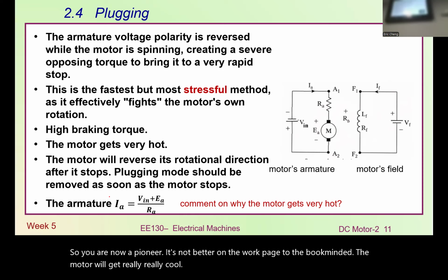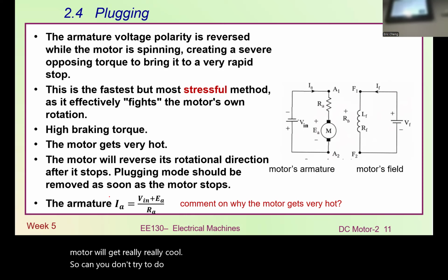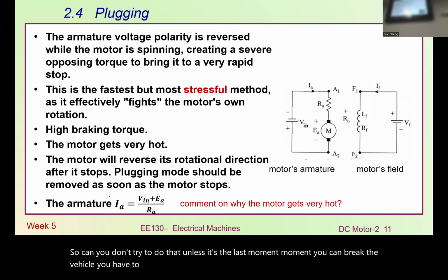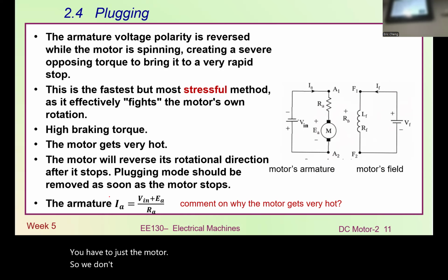So you don't try to do that unless, at the last moment, you cannot brake the vehicle and you have to use plugging mode for instant, sudden braking of the vehicle or the motion. So we don't use that until the last millisecond, when the current builds up.